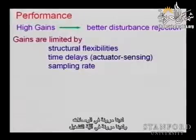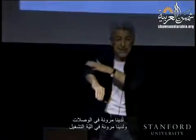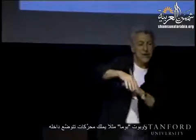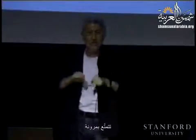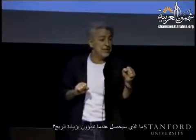We have flexibilities in the links. We have flexibilities in the drives. If you take the Puma, it has those motors placed inside, and they are connected to the joints through rods, and they have flexibilities. And when you start cranking up your gains, what's going to happen?